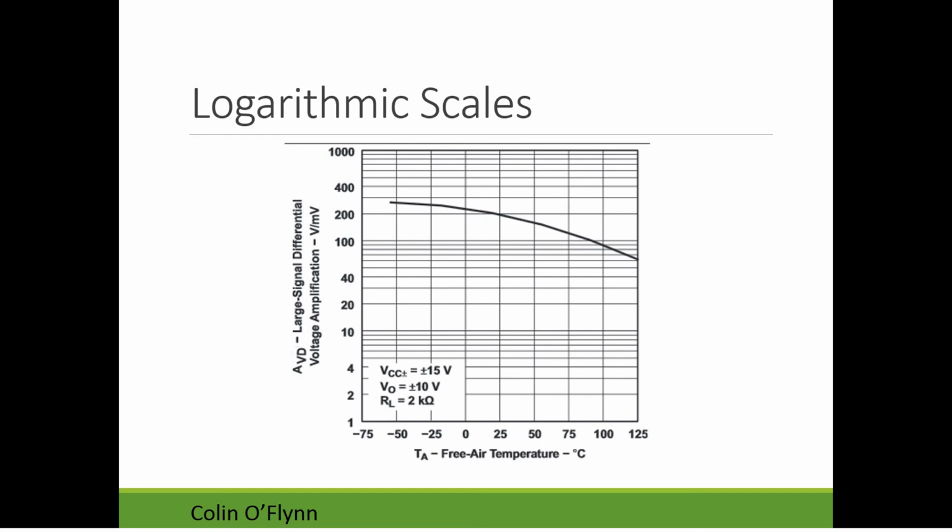And when you're looking at data sheets, this is something that came up in one of the earlier assignments. A few people had questions. I just wanted to make sure everyone knows about this. You'll often see these logarithmic scales, and we'll see them all the time in these frequency response graphs. In the logarithmic scales, you can see the uneven spacing of the axes. All you have to remember is that every increment here is based on this base here. It goes 10, 20, this line is 30.